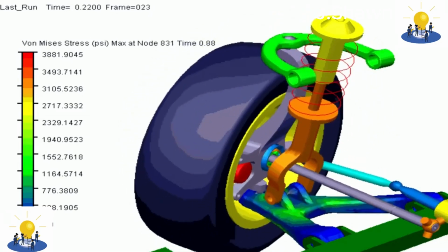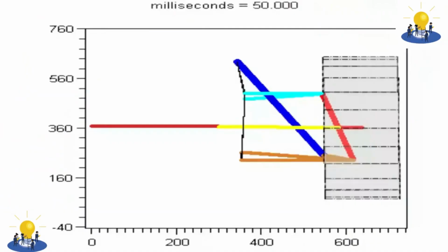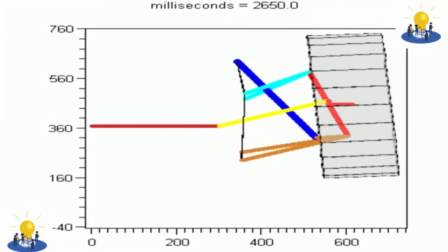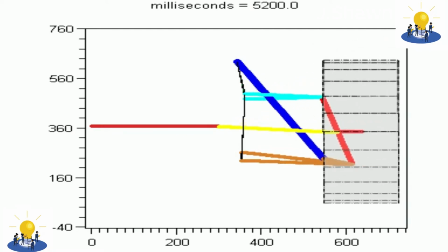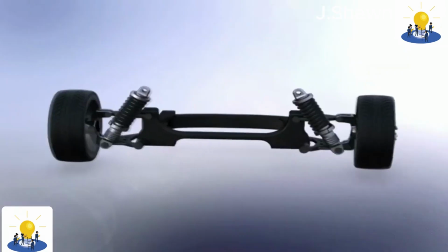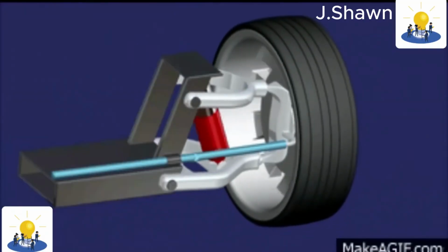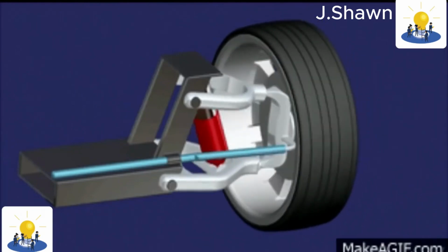Attached to the knuckle at its center is a bearing hub, or in many older designs, a spindle to which the wheel bearings are mounted. To resist fore-aft loads such as acceleration and braking, the arms require two bushings or ball joints at the body. Double wishbone suspension in action, as on display at the Toyota Museum in Nagoya, Japan.